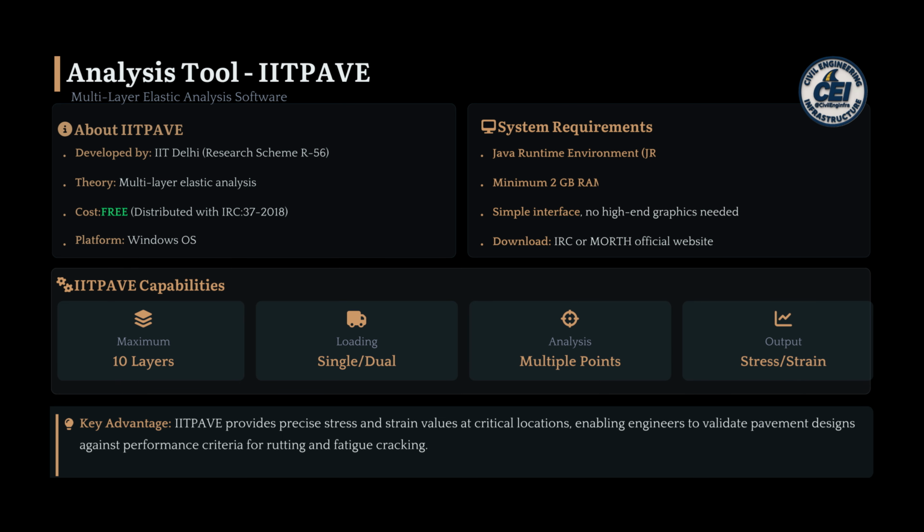Now let us come to the main topic. IITPAVE software. This is our primary design tool. IITPAVE was developed by IIT Delhi under research scheme R56. It is based on multi-layer elastic theory. It is distributed along with the IRC 37-2018 code and is available free of cost.